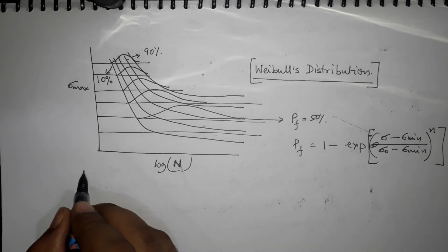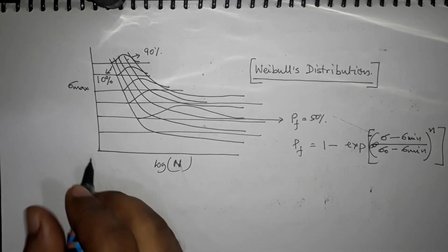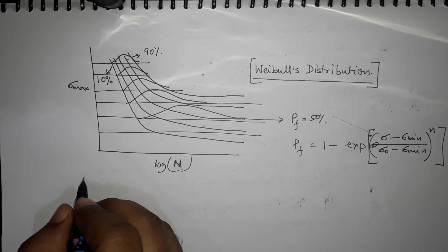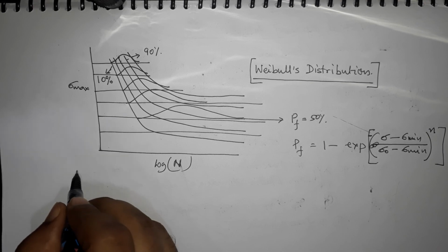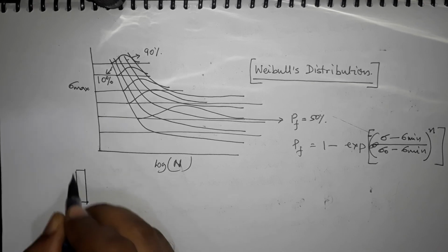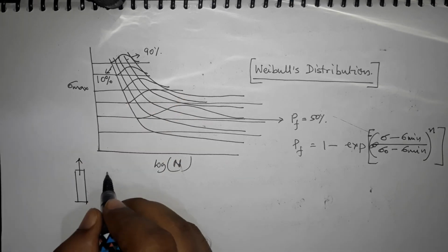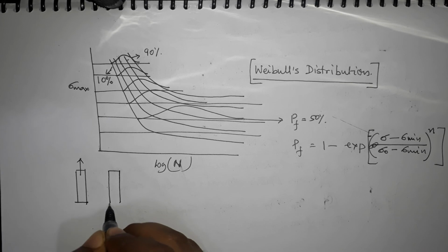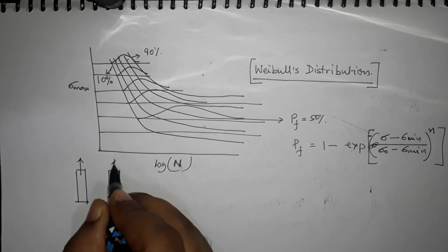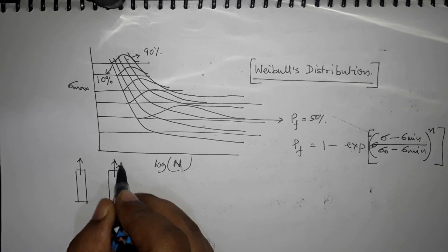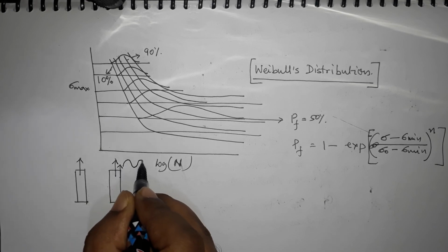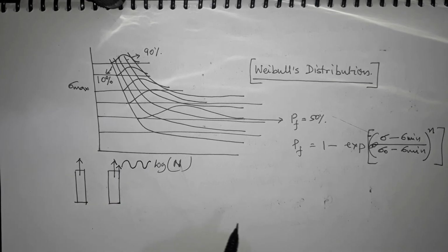So this part of fatigue was comparable to tensile testing. The only difference was, in tensile testing you apply a load and you never decrease it, you keep on pulling it. And in this case you apply a load and then you decrease the amount of load, and then you go back up and down again. Okay, so this is the difference.